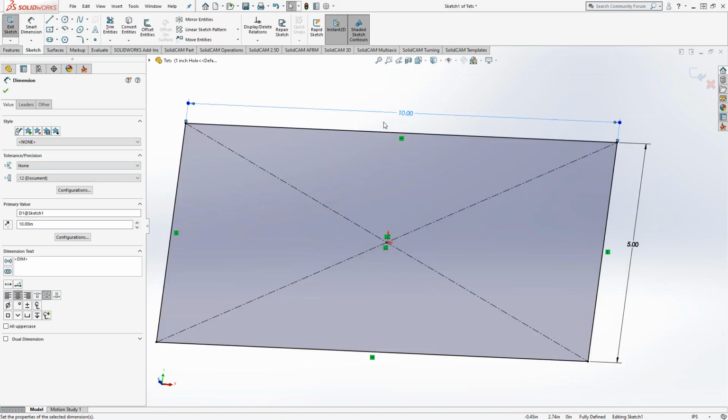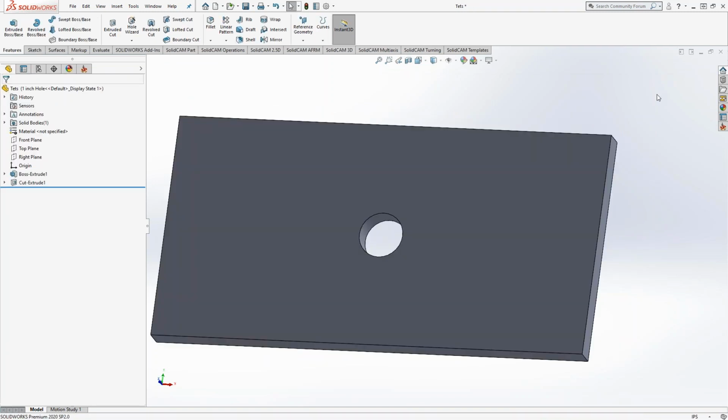The way that I designed my part, I actually have it centered on the origin there. So it's always just going to make that the center plane there. And that's another little tip and trick for SolidWorks sketching. You always want to have some sort of reference point. The origin is always a really good one to use, but as soon as you start adding additional features and you can't reference the origin anymore, that's when you add dimensions. But a dimension is a type of relationship, a type of constraint. So it also will help you in your configurations and your design.